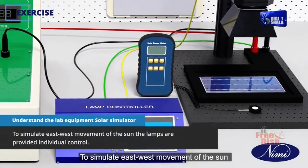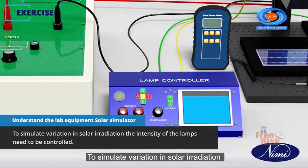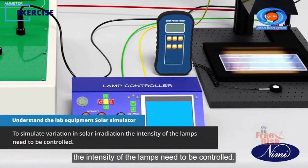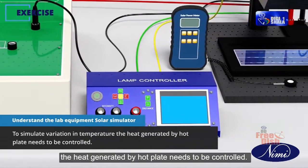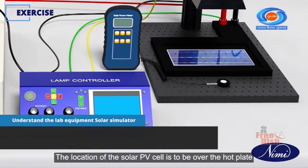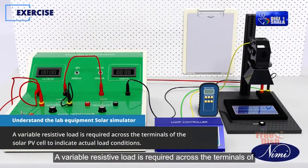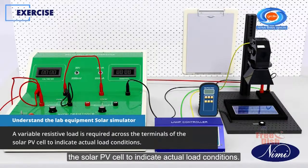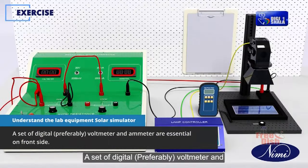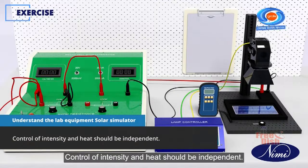To simulate east-west movement of the sun, the lamps are provided with individual control. To simulate variation in solar irradiation, the intensity of the lamps needs to be controlled. To simulate variation in temperature, the heat generated by the hot plate needs to be controlled. The solar PV cell is to be located over the hot plate facing the lamps. A variable resistive load is required across the terminals of the solar PV cell to indicate actual load conditions. A set of digital meters, preferably voltmeter and ammeter, is essential on the front side. Control of intensity and heat should be independent.